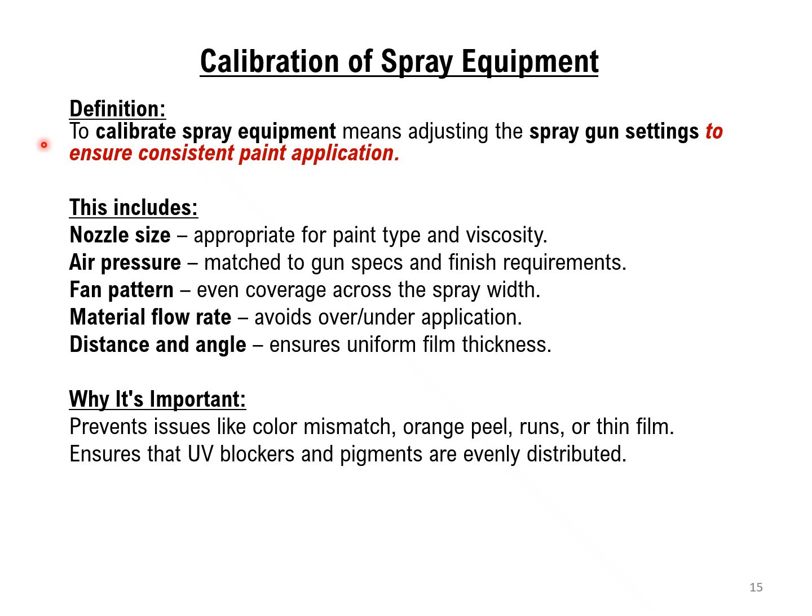This includes nozzle size, appropriate for paint type and viscosity; air pressure, matched to gun specs and finish requirements; fan pattern, even coverage across the spray width; material flow rate, avoiding over and under application; and distance and angle, ensuring uniform film thickness.